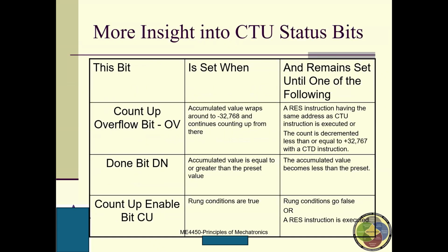So there's more insight into the CPU status bits. You can see that these are the 3 most important bits. For us, the counter done bit is very, very important because we usually use the done bit to control something. Then there are the counter up overflow bit and the counter up enable bit, so you can just take a look at these.